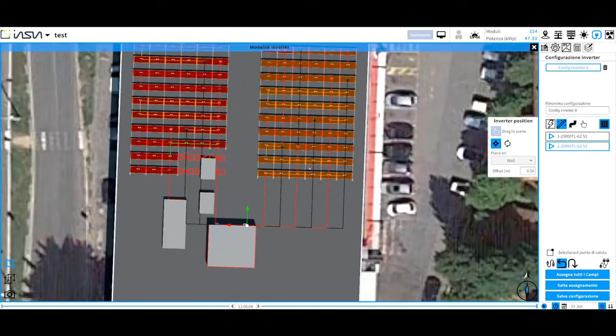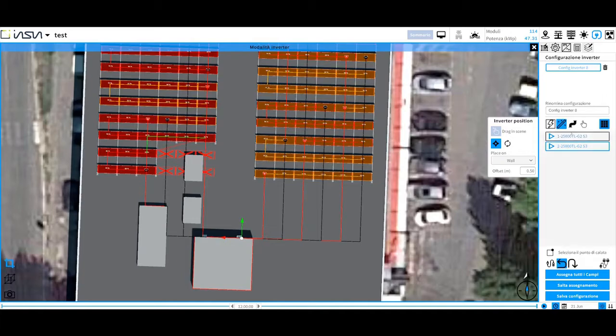As you can see, the cables that go to the inverter follow trajectories that are not ideal, or in any case do not correspond to what will be a real arrangement. We therefore need to intervene, by placing some cable ducts. We find the raceway system by clicking on the third icon, above the inverters. We can now go and click on Draw Cable Ducts.